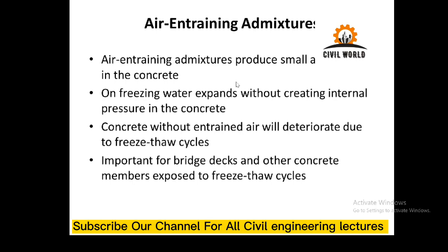lower temperature on the concrete, or when concrete is exposed to freezing and thawing cycles, because when water seeps into the concrete and then the temperature falls below 0 degrees centigrade, the volume of the frozen water increases. Once the volume increases, it exerts pressure inside the concrete, leading to internal cracking.